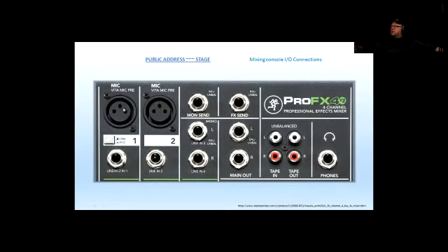If you have something like a keyboard connected to either one of those, you can take the pad out, and usually the pad takes the signal down, not up, by 20 dB. Remember 3 dB is half the power, and if it takes 20 dB, you can just do the calculations here.